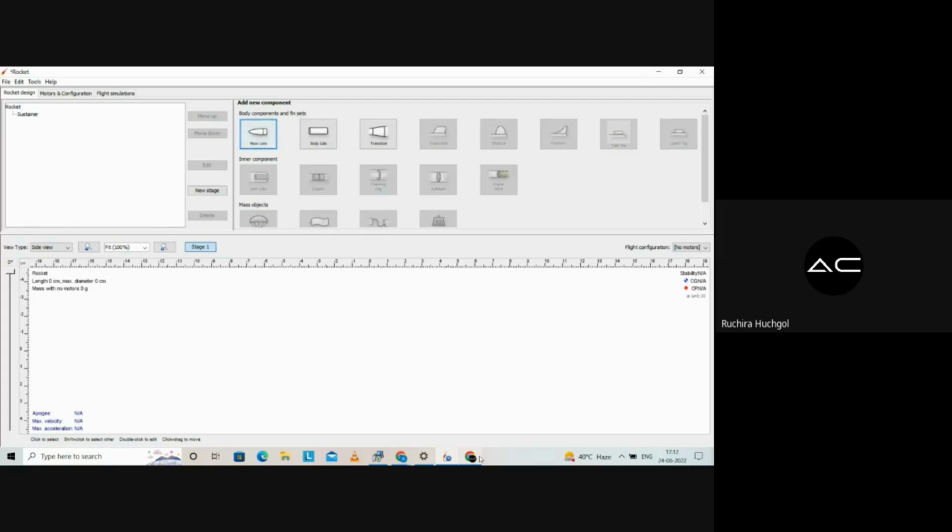So what happens is, consider a fin structure. The very small tip of the fin, air flows over it. Now that gives certain pressure and it generates a small amount of lift. But due to the generation of a small amount of lift, we also experience a small amount of drag, which adds to our total drag. Now this small drag is called the induced drag. We want to reduce that drag because we do not want our vehicle to slow down, right?